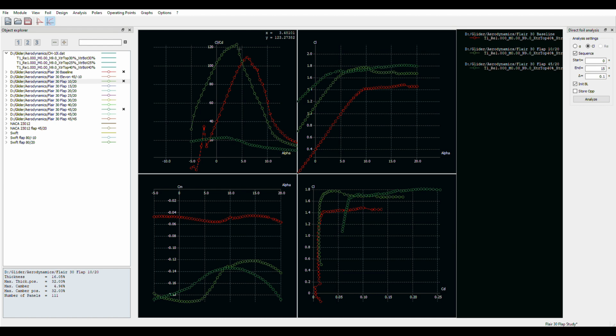oh, what do I got here? What's it showing? About 3.5 degrees here. So that'd be not too bad. I mean, it's not a good airfoil to start with, but a flap deflected 20 degrees near the trailing edge would actually help you out. You got a better L over D, and your stall angle of attack, well, once again, it's going up here and it's kind of wandering off.